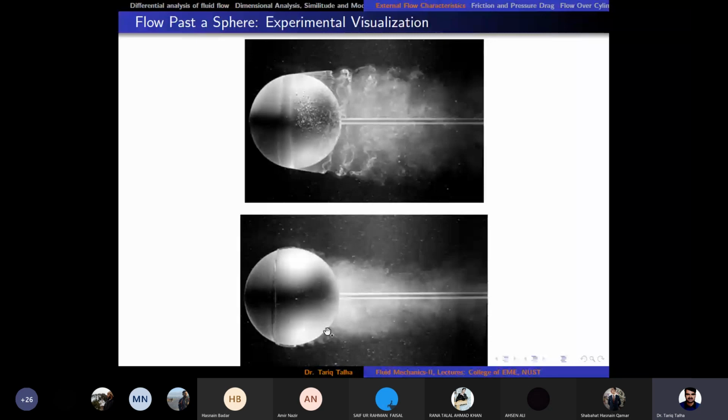So on one side we have got a vacuum due to flow separation, and on the other side we have got flow attachment due to the turbulent boundary layer. So if the upper side is shiny and the lower side is rough, the ball would always travel towards the shiny side, because the shiny side has got flow separation and the rough side has got the boundary layer attached due to turbulence. So that is the case of reverse swing in a cricket ball.